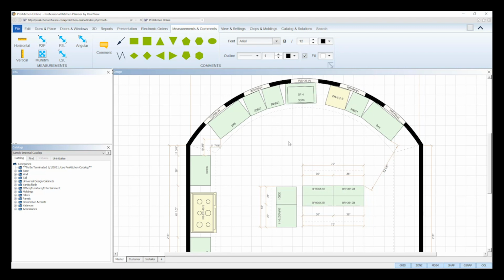The P2L tool, aka point to line, measures the direct distance between a point of one object and the line of another object. Hover your mouse over the point of your first object and then click once. Now, hover your mouse over the line or edge of your second object and then click again. The direct measurement between the two will be displayed.